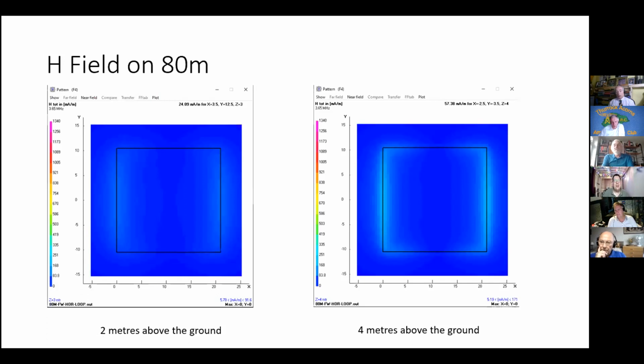You will have similar field strengths at the end of a dipole or quarter wave, whatever frequency you're on, for the same power level. Effectively the electric field strength is driven by the voltage at the end of the elements, which is determined by the power going in. So 2 meters, 2.5 meters is probably right for 100 or 200 watts.